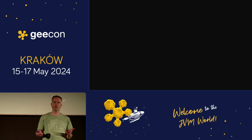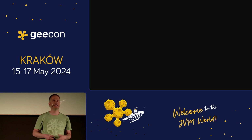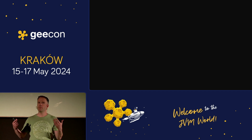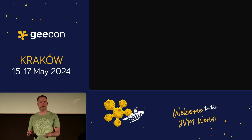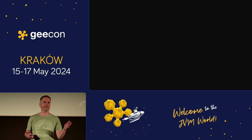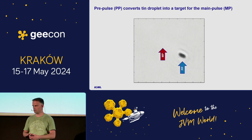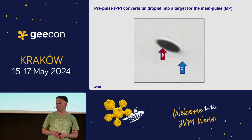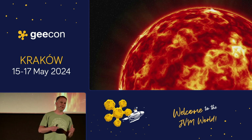And it hits each droplet of tin twice. First, softly, so that it gets the shape of a pancake, and then it hits it hard, and then that droplet of tin will result in plasma, which emits ultraviolet light, extreme ultraviolet light. So it's crazy to imagine, right? At 50,000 times per second, droplets of tin are hit twice, without tin splattering around in the machine and things like that. This is how it looks like in the video. It's not a UFO, it's a droplet of tin that's being hit twice. So it's quite a weird process.